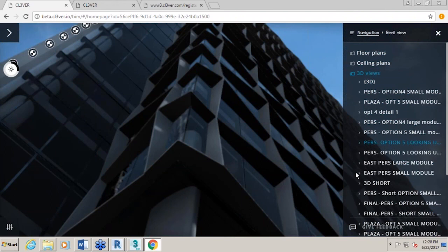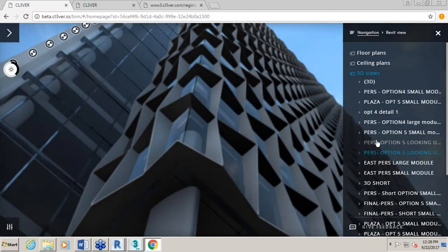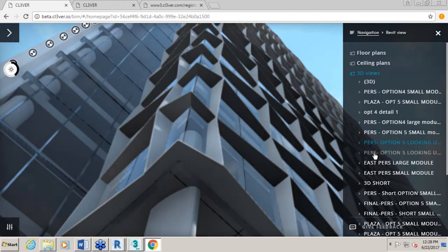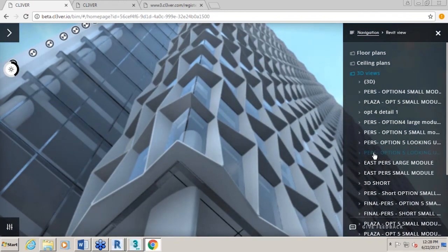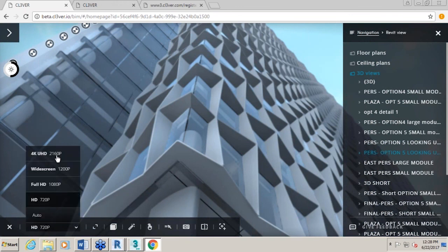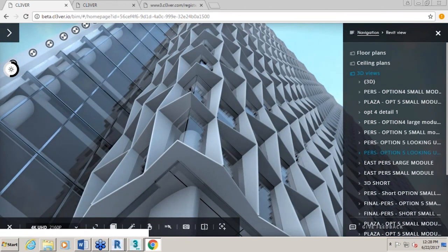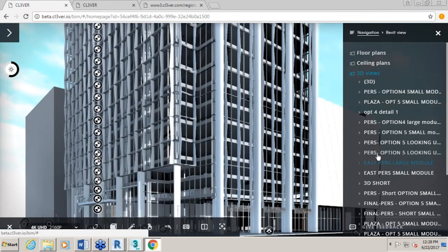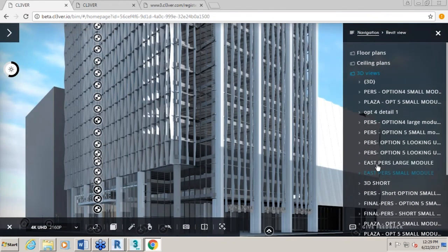So I wanted to show you another thing we talked about earlier, in Revit, that if you have design options, which we've got coded on 2 different views, right? When you enable those different views, you actually carry design options in, so we can explore different furniture layouts, building skin alternatives, like in this example. And it's carrying this right from Revit, so we're not doing anything extra to get that functionality. It's just coded by the view, so when you have your 3D camera, whatever view settings you've got, they're going to carry through.